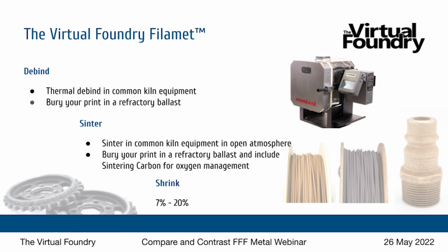So with our strategy, you can control both the density and the amount of shrinkage. Basically, the longer you apply heat or the more heat that you apply, the part becomes more and more dense over time. So you can control the shrinkage and the density and the porosity with your sintering cycle. Okay, thank you for that further explanation. I've thrown a lot of information at you at once.